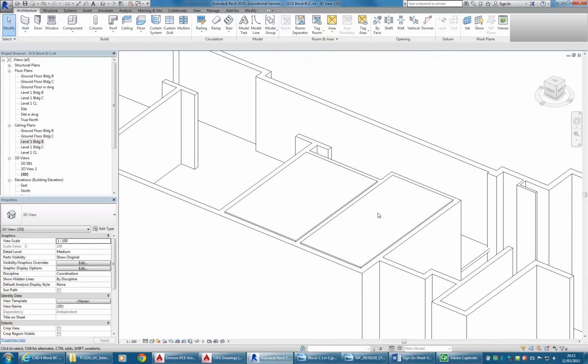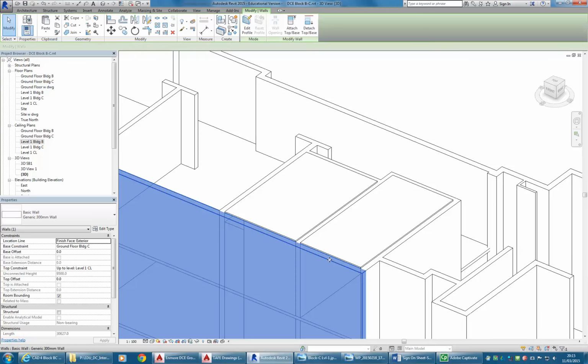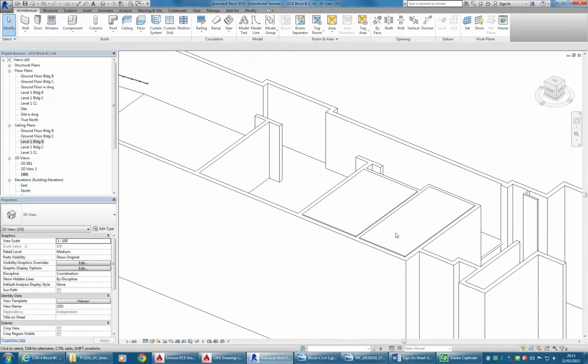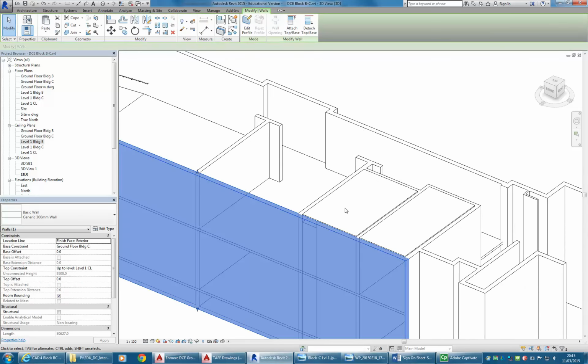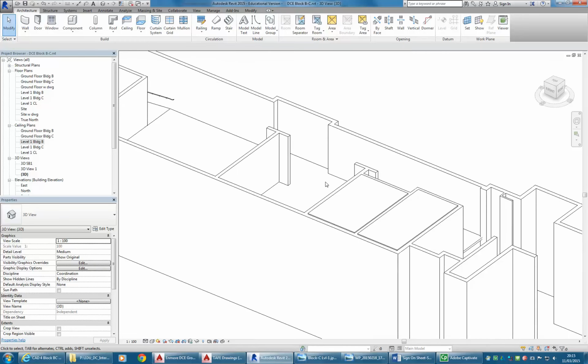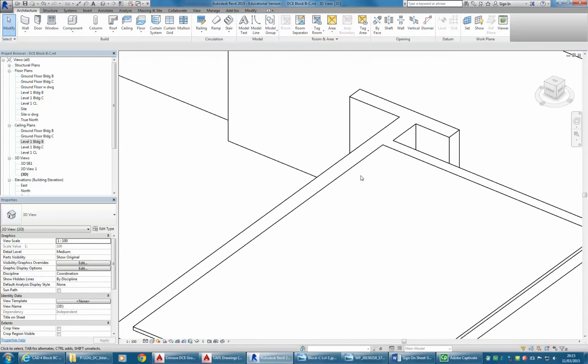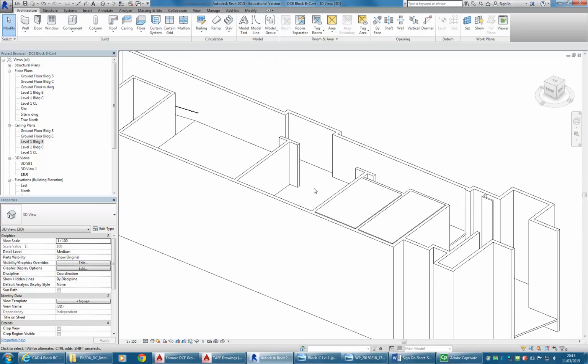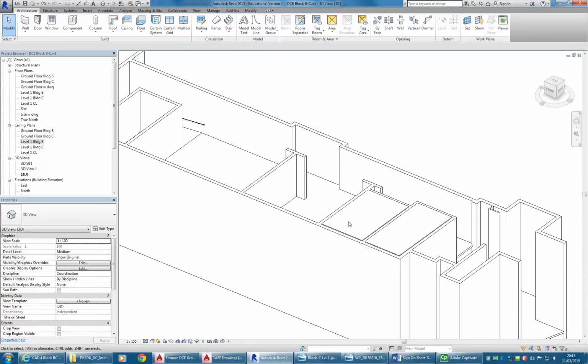And so then finally, you might need to think about what's happening with those walls going up past the ceiling, because there's a good chance that they do go past the ceiling. Now I wouldn't start changing them right away, I'd wait until you put the roof on, because the roof may hide a lot of that. So for now, if you have the ceilings at the height that the wall terminates or finishes, that's going to be okay. So that's for the upper level.